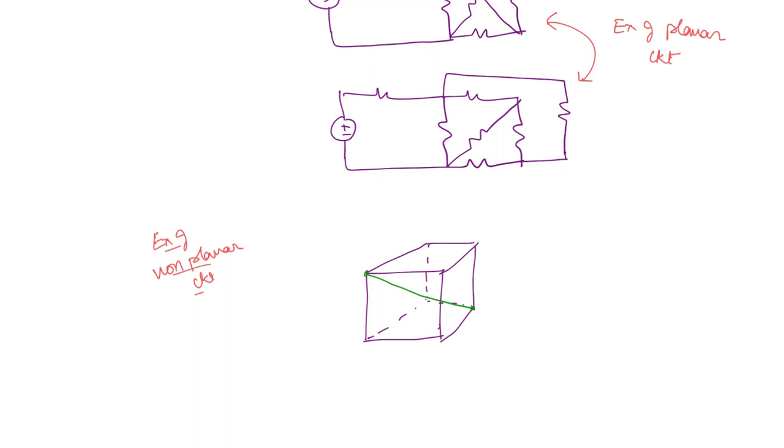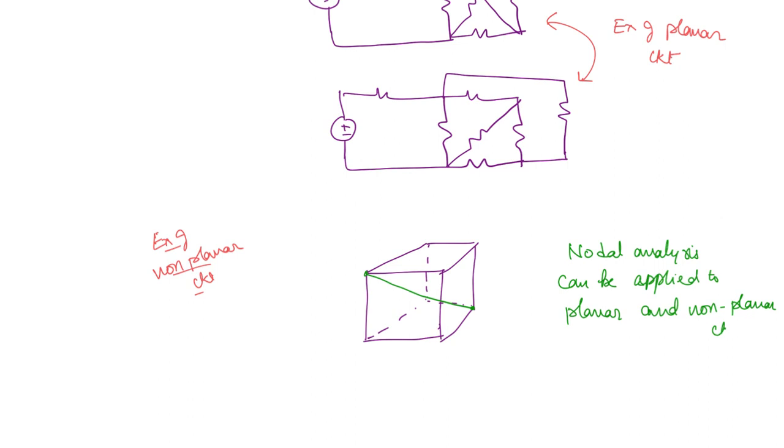Now mesh analysis cannot be applied to this, but you can apply nodal analysis. Okay, so this point is important. Nodal analysis can be applied to both planar as well as non-planar circuits, and that is not the case with mesh analysis.